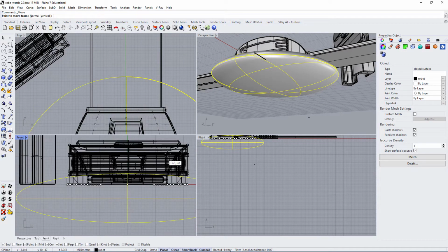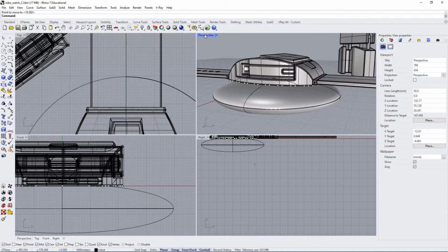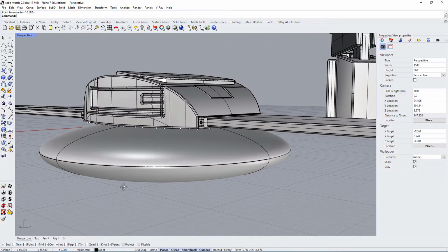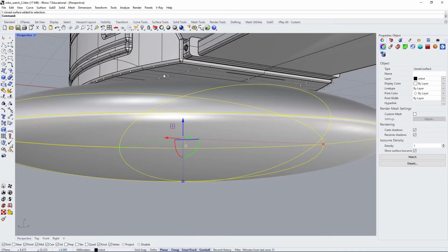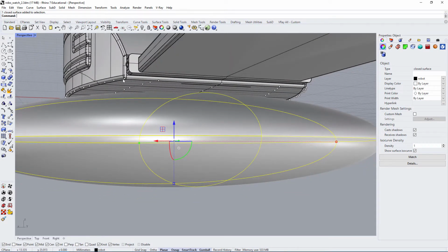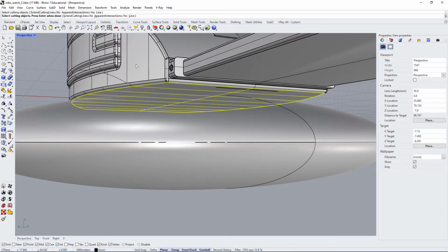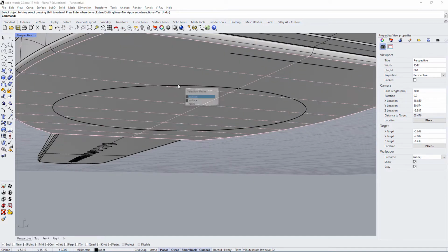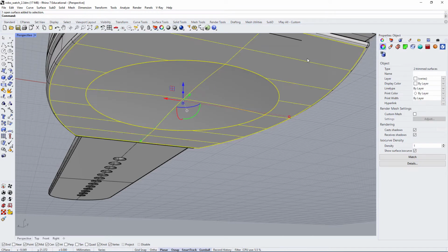The reason for that is because the sphere is kind of like your radii, your fillet surfaces. They basically have a radii, right? They're a distorted circle. They used to be a circle, and now you scaled your circle to be a different shape. And so this can cause some major issues. You could do a boolean, you could trim it, but usually you end up with some issues later down the line. So let me go in and cut. We'll cut this. Okay, accept. Then I take this circular surface and I can run the same command again. Trim this. Okay, and then I can join them.